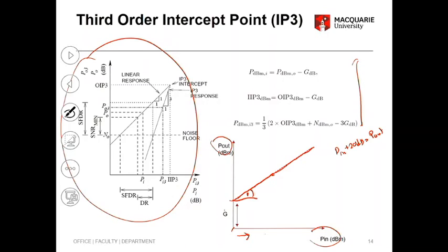Question? Okay. Now after a certain level, you tend to see your third order intermodulation products coming above the noise floor, because initially you won't notice them because they are below your noise floors and it's adjacent channel anyway, but then they tend to creep up. Say for example at a particular input power, on this axis you are measuring output signal. This is your desired signal power level. Then at a certain higher power input, you have two inputs, you have two outputs, then you tend to see this creeping up.